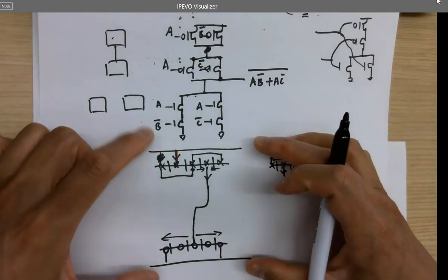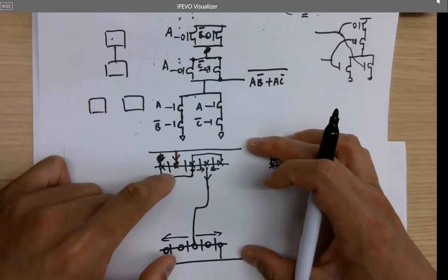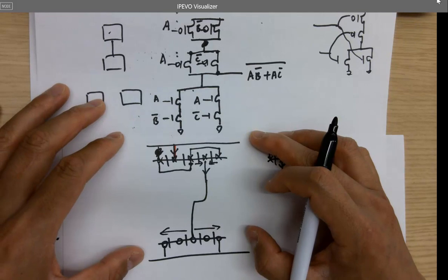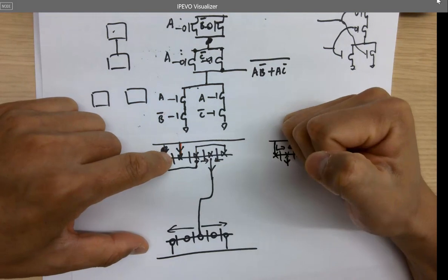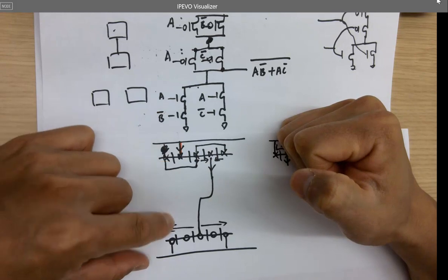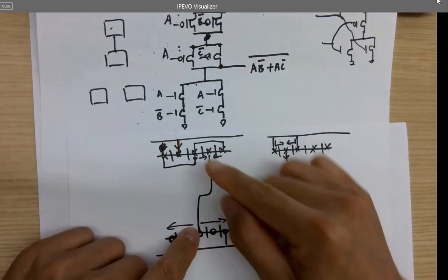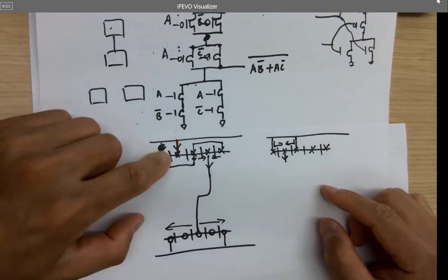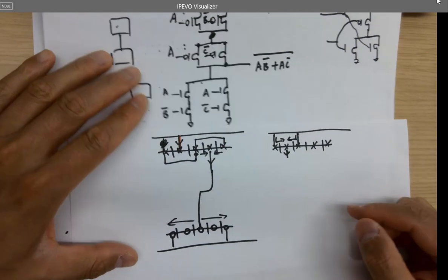After laying out this circuit, you should know which gate should be which signal. Let's take a look at it. You cannot randomly name them because you are hoping that the gate here is the same signal as the gate here. So you can directly just draw a straight line. You know what I mean? You don't want to draw, this is A, let's connect this way, and then let's connect this way. They are going to short to each other. So the best way to do it is this A, B, C, D. Let's check if this is correct.